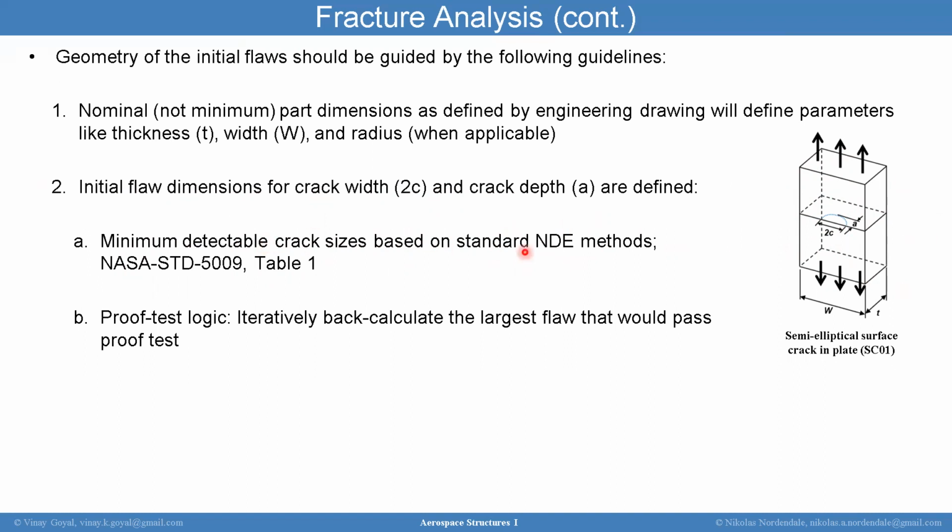Another approach to size a flaw is to calculate the largest flaw you can ever have that passes the proof test, and then use that flaw to determine whether the structure has sufficient life throughout its service life.